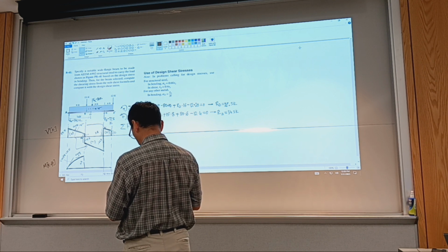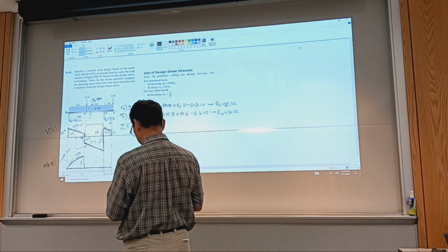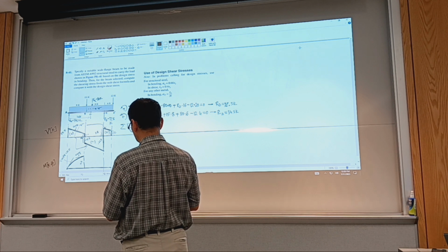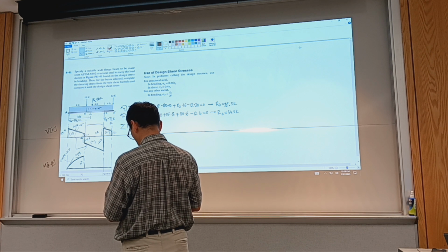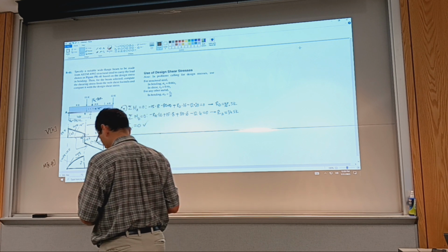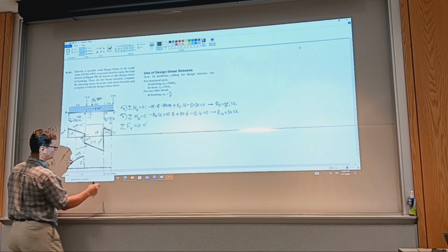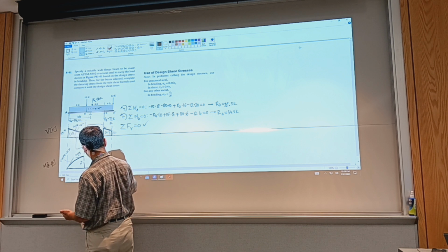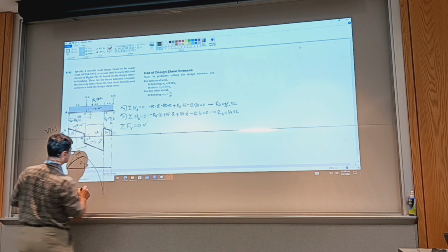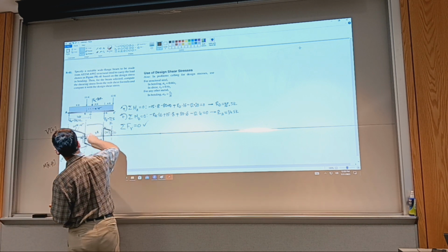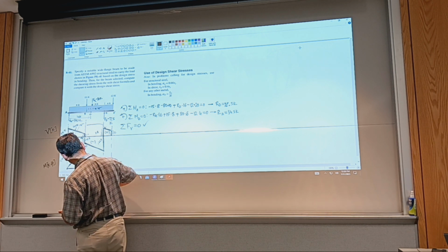So it'll be 12.5 plus 44.5 times that distance, 8, over 2. This is a negative value, plus what was earlier, 148, gets us negative 572. Okay, so it goes from 148 to quite a bit of negative. Okay, so it went this way. All right, starting with a slope of 12.5 here, going all the way to a slope of 44.5.